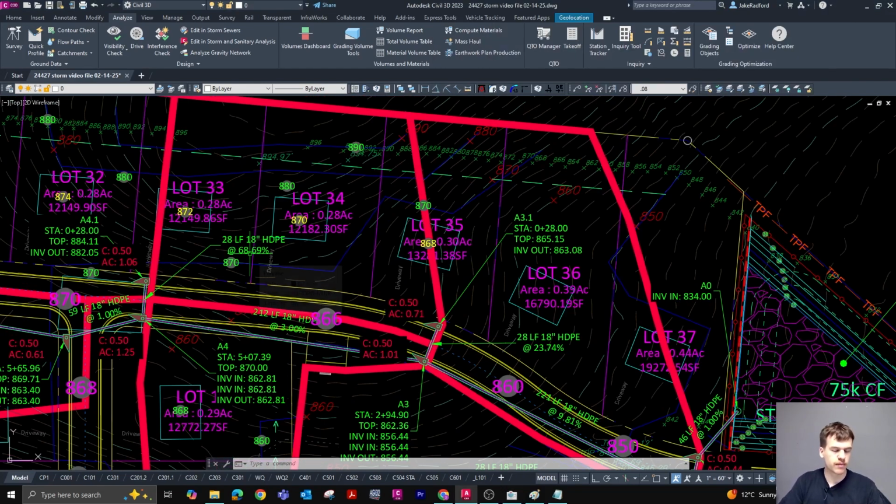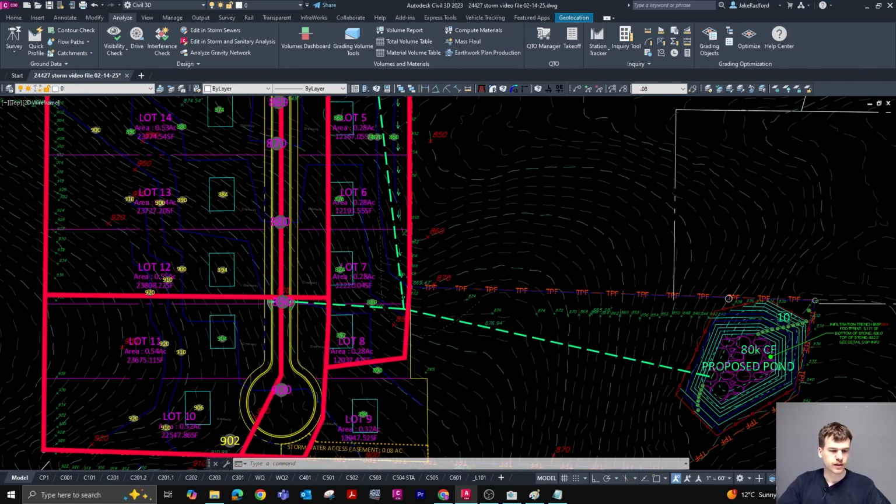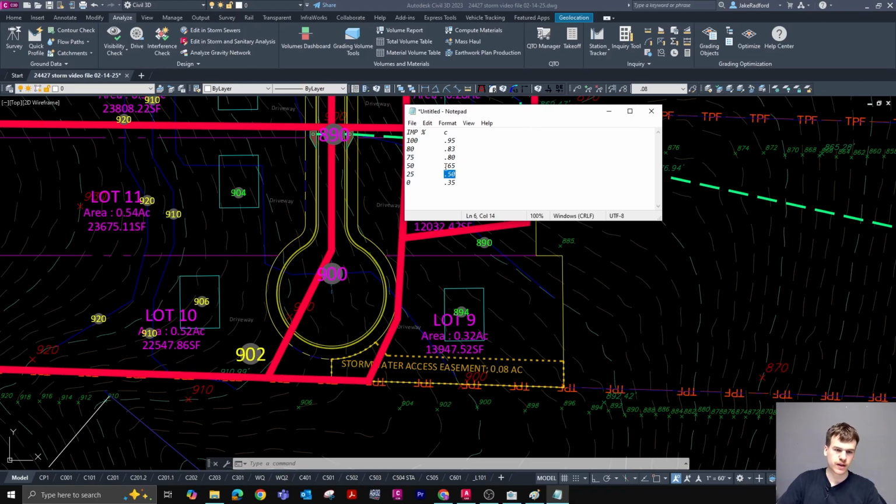Again, if we had maybe a drainage area such as this one right here, this drainage area down here on this southern pipe network. Nearly half of it is taken up just by the cul-de-sac, and then plus it might have some drainage if we adjusted it and included this house. So that's definitely 50% or more impervious, so the value for the C would be 0.65 versus 0.50.